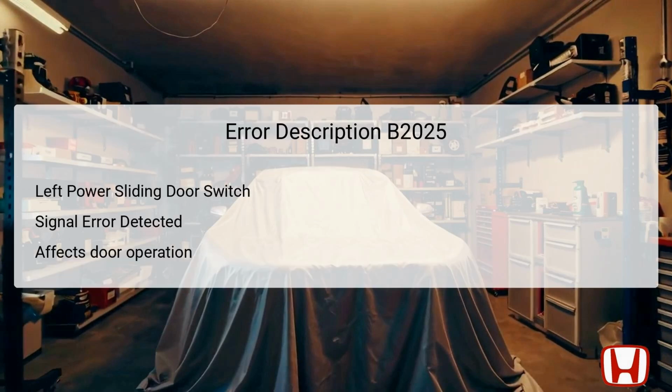The B2025 error code describes a left power sliding door switch signal error that can impede the operation of the power sliding doors. This switch is part of the power sliding door mechanism, which is responsible for signaling the control unit to open or close the left side door. When the signal is not received correctly, it results in this error code.